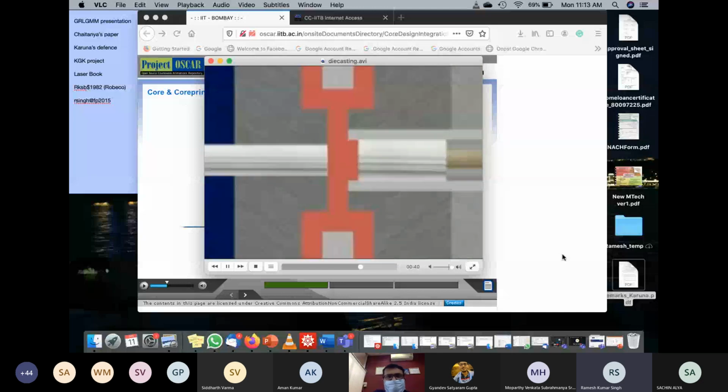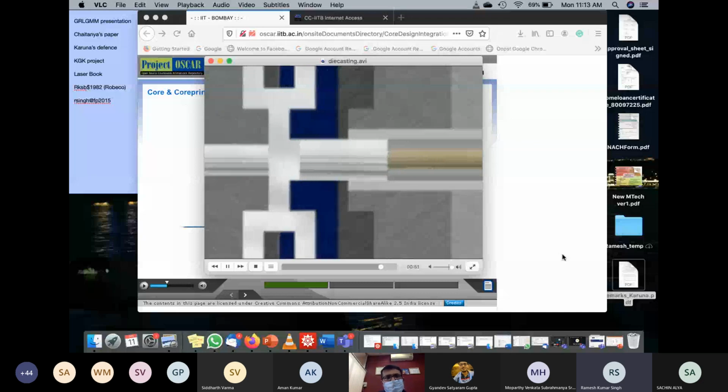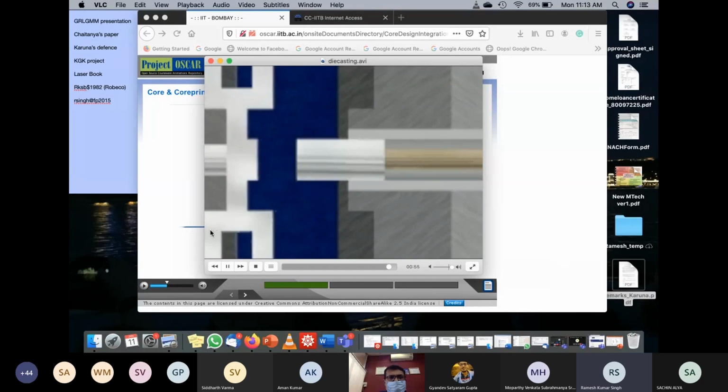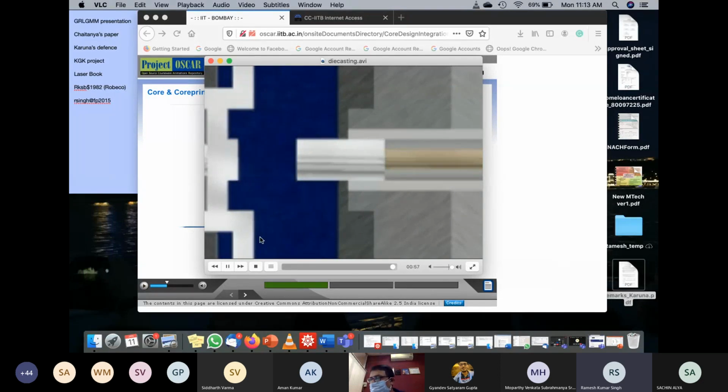So that it fills the cavity. So the die, this is the shape you have to create, right? The die halves are separating, so you have to fill the material there. The plunger thrusts forward, extending the plunger tip past the cover die. Okay, this pushes the biscuit, which is your part, that solidifies at the end of the shot sleeve, assisting casting release.